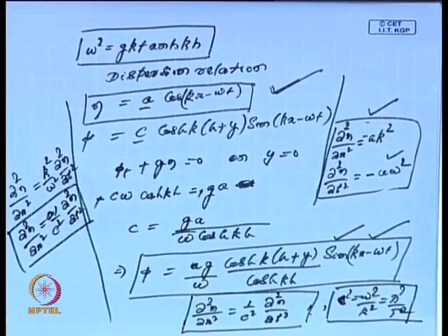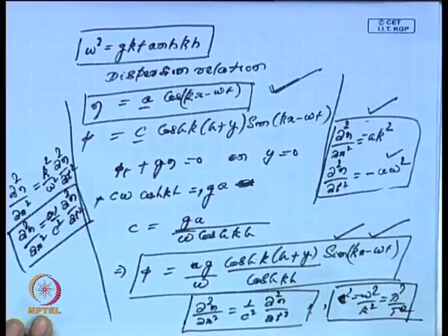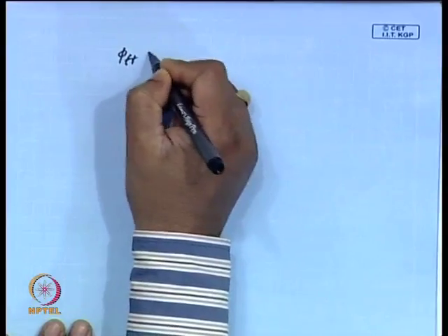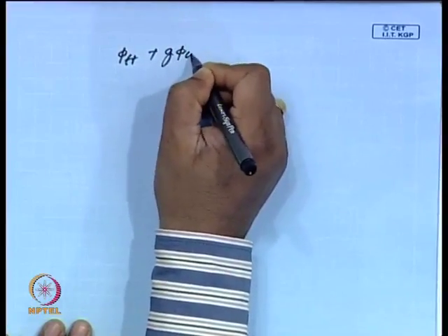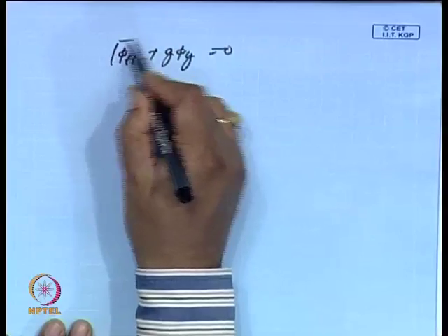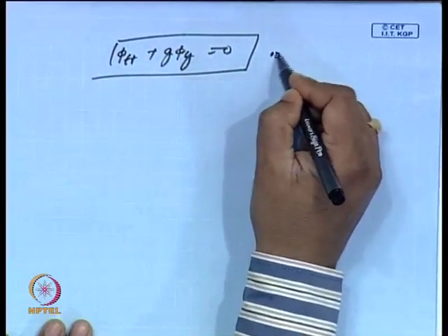So, that means I have a wave, but I am not solving a wave equation. This is the question that comes. What am I solving? I am solving the Laplace equation. Then from where is the wave coming? The wave is coming because I have a free surface condition where the gravity term is there, because in the free surface condition we have seen we have a term like phi t t plus g phi y is 0, at y is equal to 0.